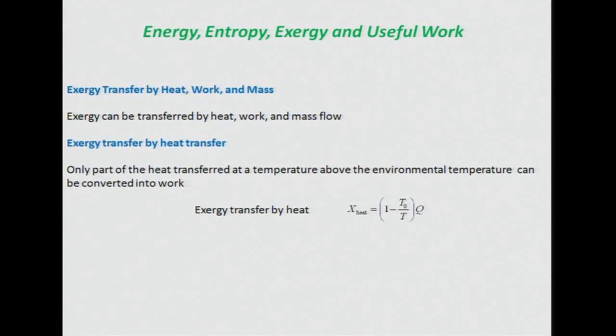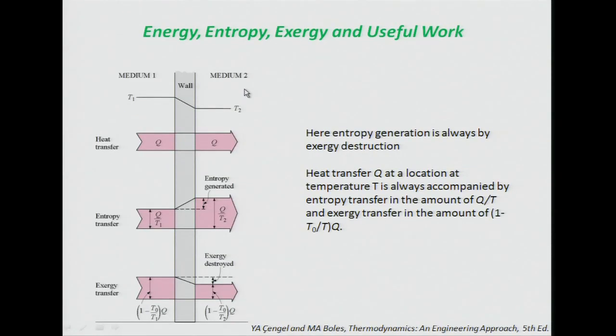Okay, we talked about energy transfer. We can transfer energy by heat, work, and mass, and exergy is a form of energy, obviously, so we can do that. We talked about it before, we just defined it again. Exergy transferred by heat can be calculated simply by taking the heat flux here and multiplying it by 1 minus the ratio of the environmental temperature to the temperature of your system. For example, let's say you're looking at heat passing through a wall.